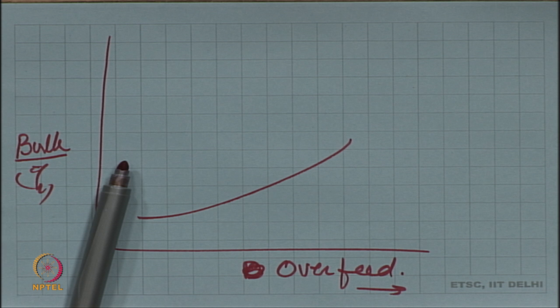So, they can bend. You may not like the yarn as such, because instability is not good, but this fellow is trying to just keep increasing its bulk. So, the effect of increasing the overfeed is to increase the bulk. Otherwise, how would you come to this conclusion? Everybody said this. So, bulk is increasing. Obviously, there may be some larger loops which may not be contributing, but some smaller loops are contributing, which are also being generated.